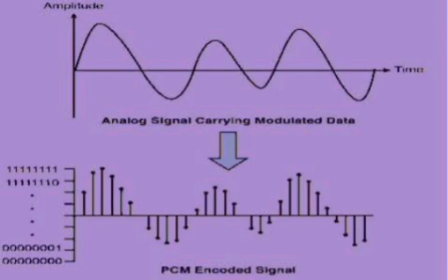Complexity of coherent schemes is always high compared to non-coherent schemes. Coherent schemes have less probability of error compared to non-coherent schemes under the same conditions. ASK scheme has the lowest noise immunity against noise. PSK is the best among all shift keying schemes. Coherent schemes require lesser power compared to non-coherent schemes for the same probability of error.